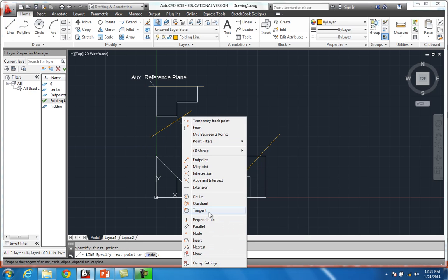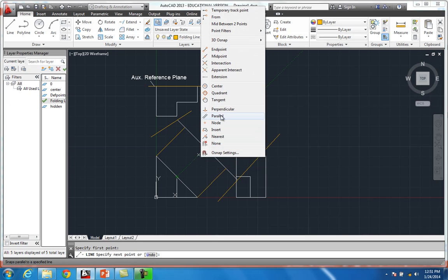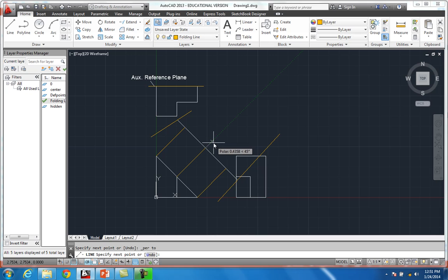Make sure you're perpendicular to this line. I go ahead and send all those up just like that. Now we just need our depths, and this is the easiest way to do that. Just come up here, measure from there to there: 1.4679. It's an odd number, but we'll use it.